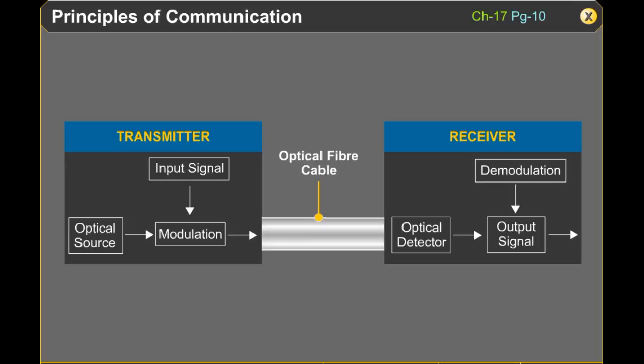Communication system. The input analog signal is first sampled and modulated using pulse code modulation, which results in discrete pulses and gives coded streams of bits representing the signal. In the bit stream, the optical beam from a source is modulated, producing a modulated optical signal. This modulated signal propagates through a medium called optical fiber.